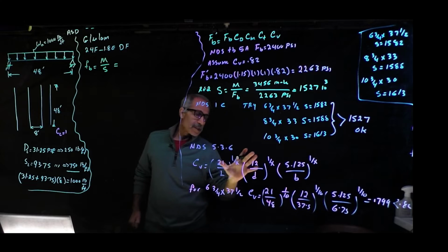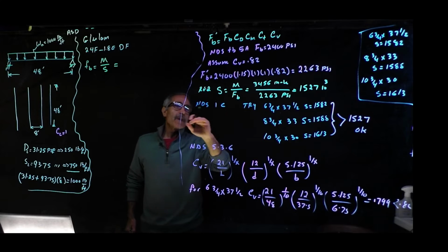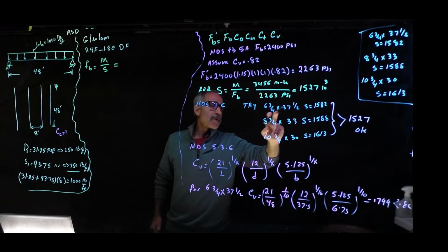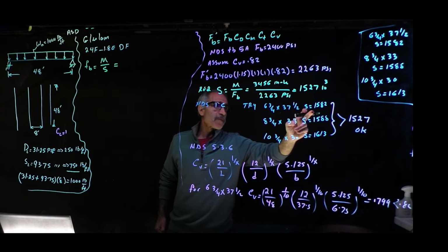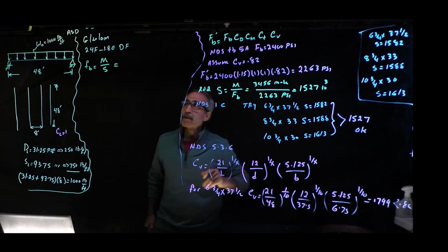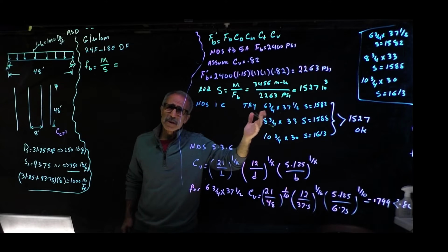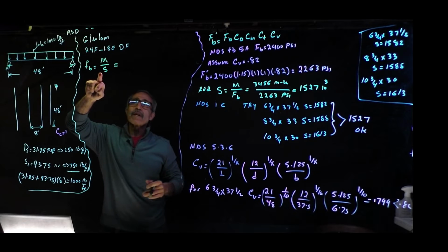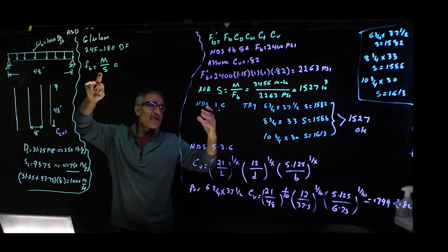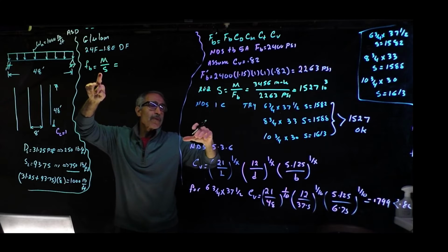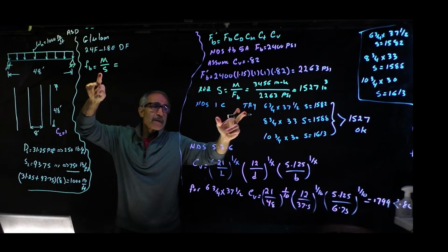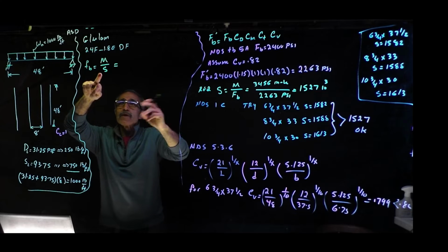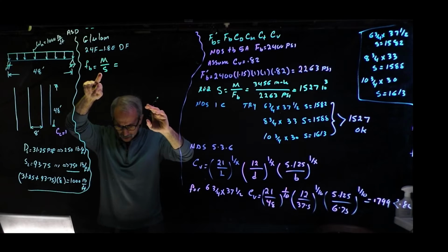So now we selected this size, and we found out that this beam that we're selecting is 6 3/4 by 37.5, and we're going to use the section modulus of 1582. That's what it is for that beam, which is S equal to b d squared divided by 6, or you can pick that from a table. So now we have that. We're going to go back and see what the stress due to the load is for this beam size. Our moment we calculated, which I erased, you have it, or go back and you can see it, and that was what? That was